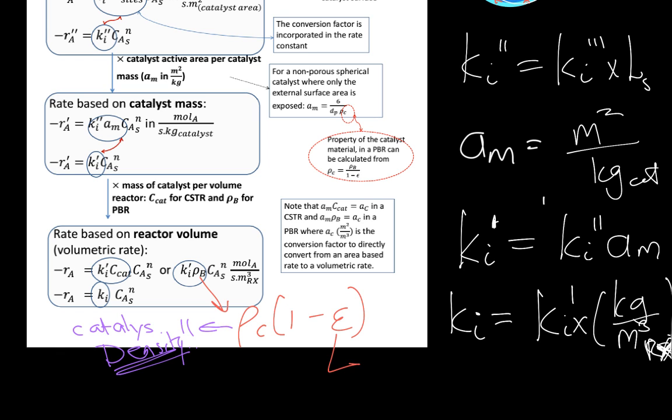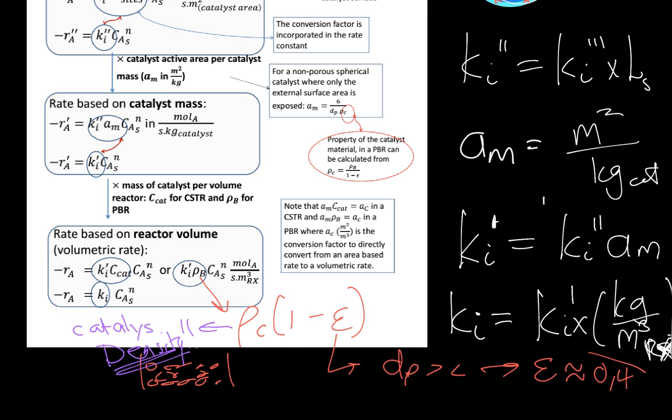What we should note is that if I have spherical particles and a big enough wall to particle ratio so that the wall does not affect my particle structure, even if I make my particles bigger or smaller, the bed porosity goes to the limit of pretty much 0.4. So that may not be as variable as you think for a packed bed reactor.